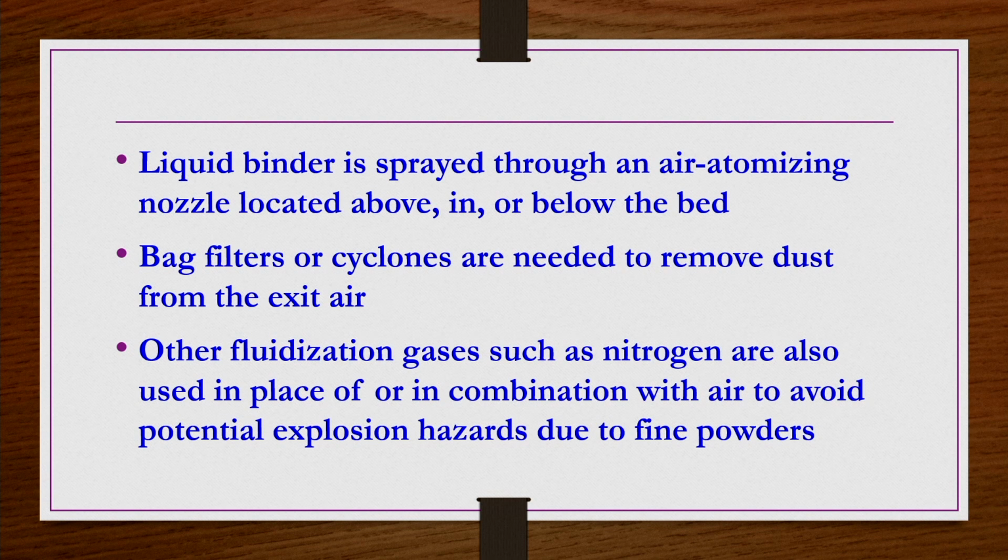Why? Because sometimes some particles are explosive, and if you are using air and heating is also involved, then a reaction may take place with the oxygen present in the air, and in some cases an explosion may take place. Under such conditions, it is better to go for nitrogen as the fluidizing medium, or nitrogen mixed with air or something like that. One has to see this to avoid explosions. That depends on the nature of the chemicals being processed in the fluid bed granulator for their size enlargement. It is not necessarily true for all materials. It depends on the type of fine powders.